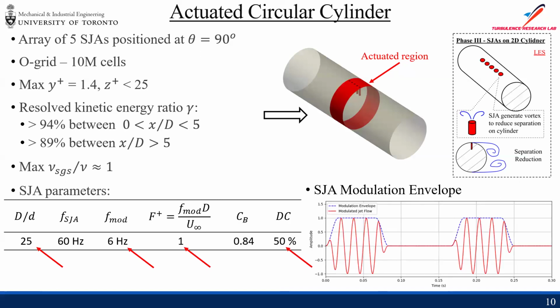And here's how the modulation signal looks on the lower right. It's actually a blend of two different functions. There's a step input, but I've tapered it off during the start and the finish of every burst cycle with a sine wave. This is primarily to combat numerical instability, where the initiation of every burst puts a lot of strain on the pressure solver. This helps the solver warm up a little bit to avoid any non-realistic behavior, especially close to the boundary condition.